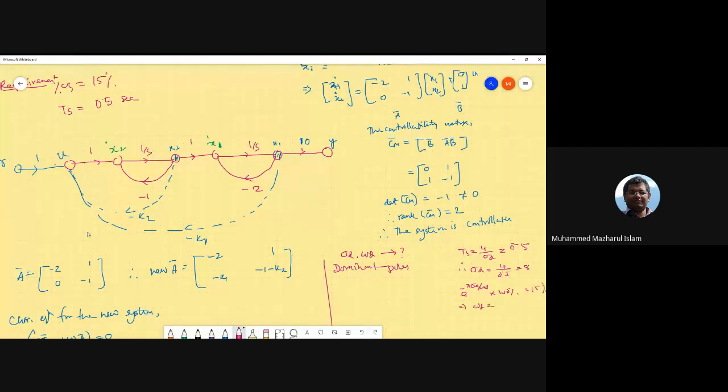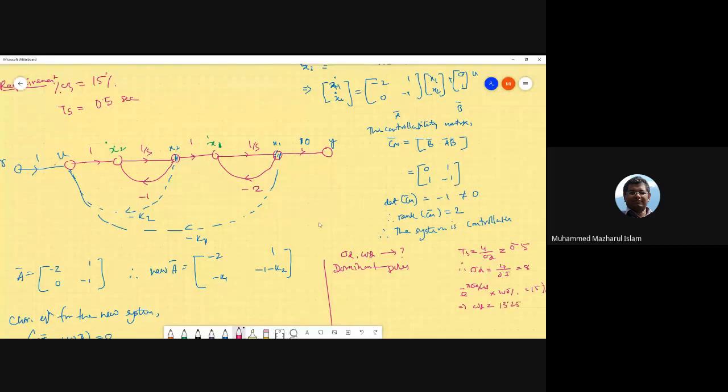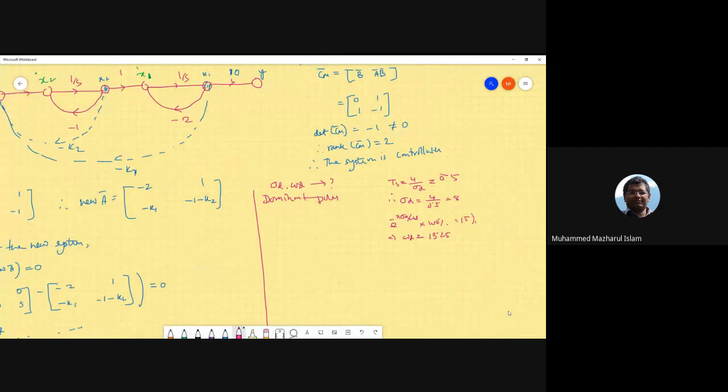I have to check the solution, omega d would possibly be around 13.25. I can write this because I already did the solution and already calculated the values. So omega d is 13.25. Now the dominant poles would be minus 8, remember, plus minus j 13.25. These are the dominant poles. It's a second order system, so I don't need a third pole.